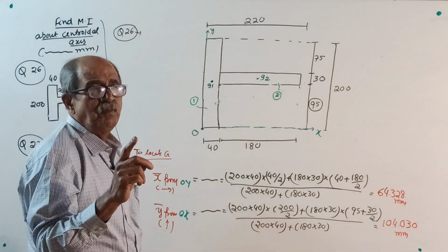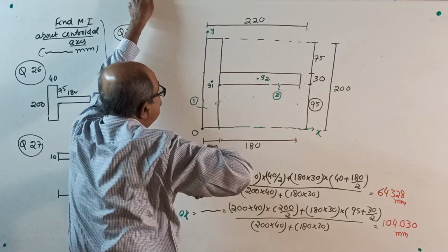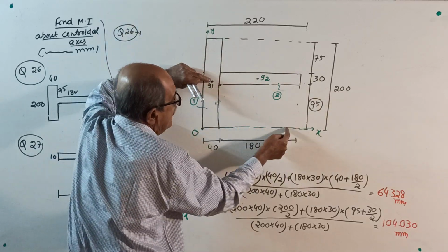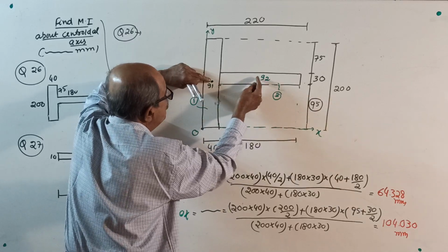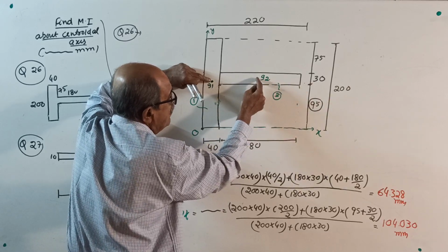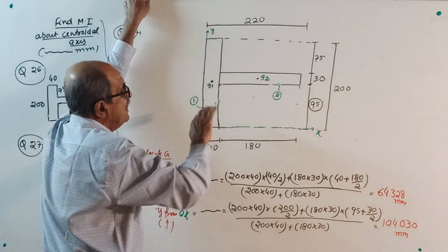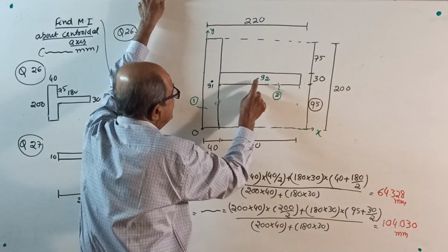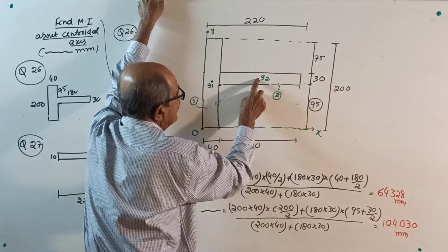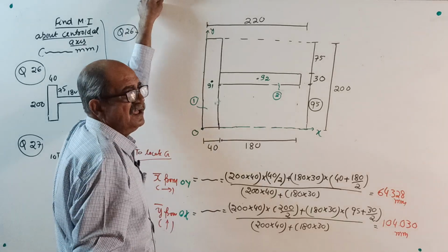Now, when you mark component centroid, this way midpoint, 40 means 20 and 20, no problem. This way, this is 200. It will be at 100 from here. 100 means 95, so slightly more. But to this level it is 90. Centroid of this level is 95 plus another 15, 110. Oh no, little below this level. See, this G1 is little below G2. Then second one, this way center G2. Where is it? 95 plus another 15. It will come here. And this way, it is exactly center of 180. These all you should make note.